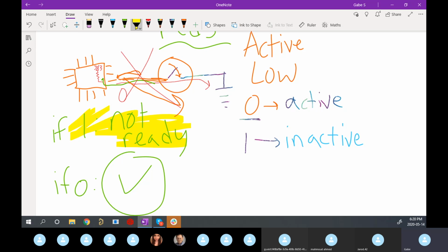And this could mean that everything's fine, but the driver's just not ready yet, or it could mean that we accidentally lost this connection and something's damaged in the car. And so it's really important to have this sort of default state that is an error, for example. This default state that won't allow us to proceed unless everything's connected properly, the driver's hit that button, hit that toggle switch, and we're good to go.